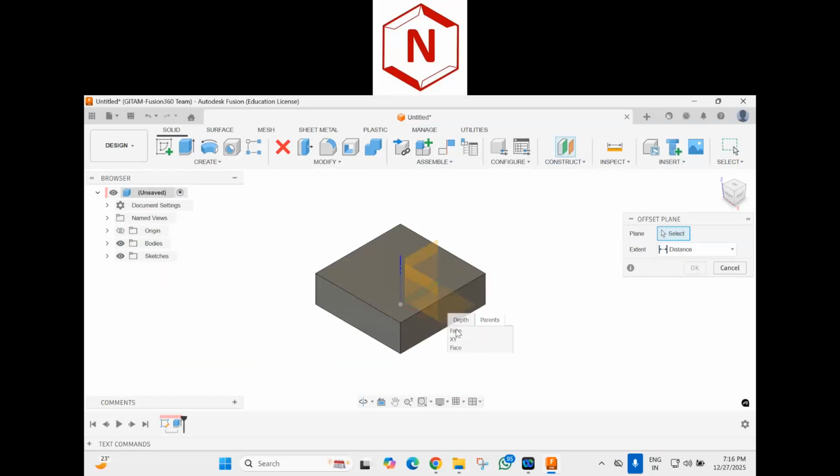If you give a long left click, it is going to open a menu like this to select various faces or the XY plane. If you click on the XY plane, it is going to select the XY plane, and now using the blue color arrow, you can create an offset plane like this. I want this plane to be exactly in the middle, so I am going to give a distance of 25 mm, and I am going to click on OK.